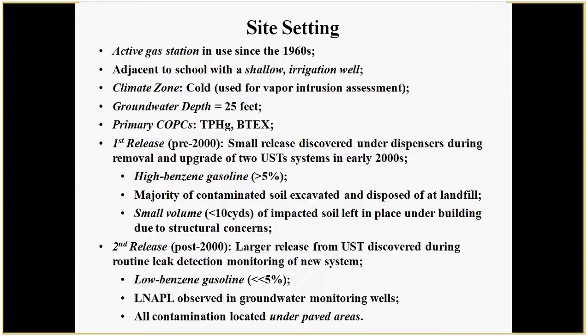Much higher risk of vapor intrusion concerns in cold climates, where buildings are heated and less well ventilated, than in warmer or tropical climates. Depth to groundwater, 25 feet. We did this on purpose. Once you get more than about 15 feet to groundwater or even contaminated soil, then vapor intrusion problems associated with petroleum tend to be less significant just due to degradation. This is discussed in ITRC's PVI document.